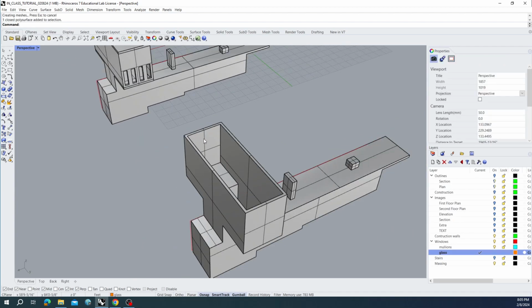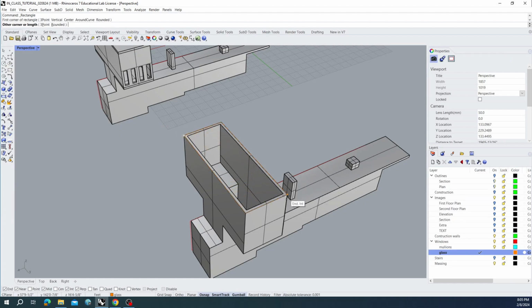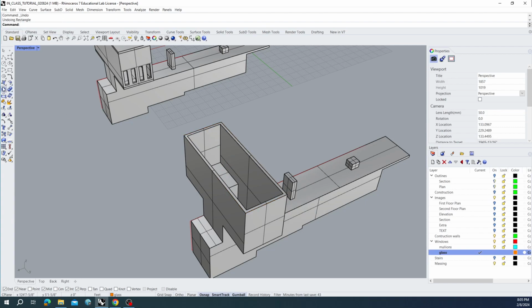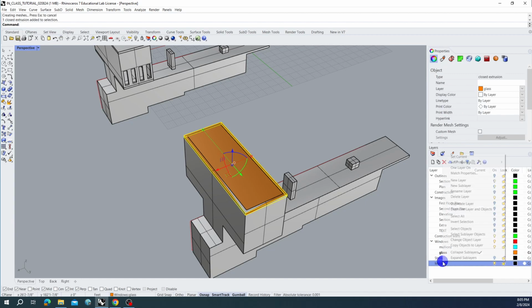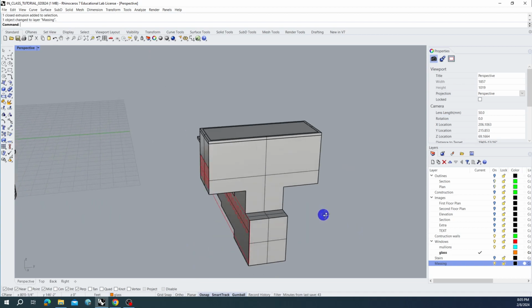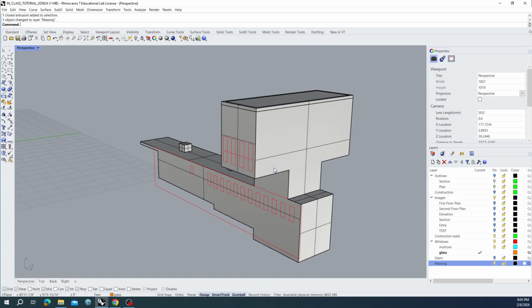You will notice that we are missing a roof now, which we can easily recreate by either drawing the curve and extruding it down 1 foot, or just drawing a box using the 3-point. Right, 1 foot. So again, we're kind of back at that same point we were before. We can extrude these windows and start modeling the interior walls based on what the floor plan is showing.